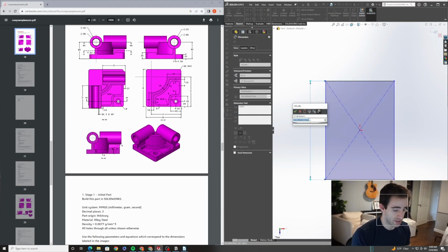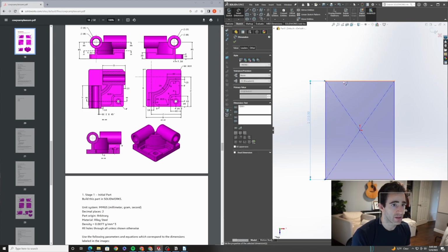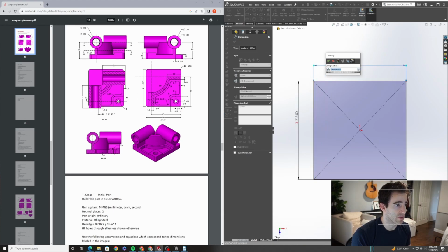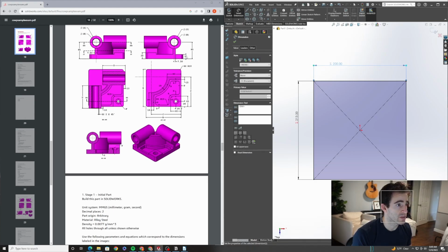And this is going to equal A. Good. B. I'm just looking at this view here to get this top view. And then I'm going to extrude 25 millimeters.